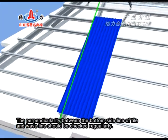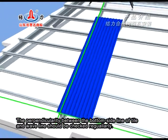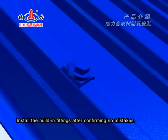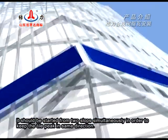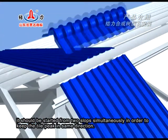The perpendicularity between the bottom side line of tile and wave line should be checked regularly. Install the built-in fittings after confirming no mistakes. During the installation of two slopes roof, it should be started from two slopes simultaneously in order to keep the tile peak in same direction.